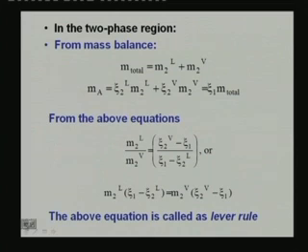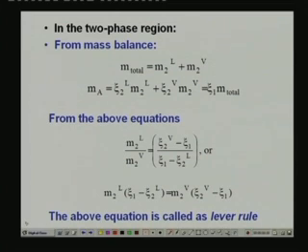And for the two phase region, just now I have explained, you can write the mass balance. So, the total mass is always conserved, total mass is nothing but M2L plus M2V, and you can also write a conservation equation for the ammonia mass. This is nothing but the total mass of ammonia in the mixture, that is nothing but ammonia in liquid phase plus ammonia in vapor phase.